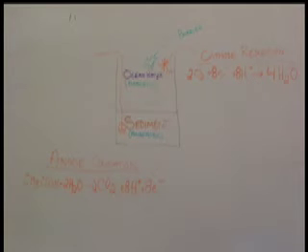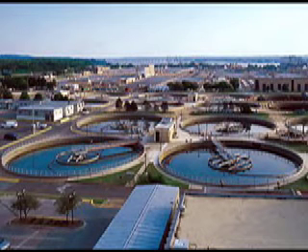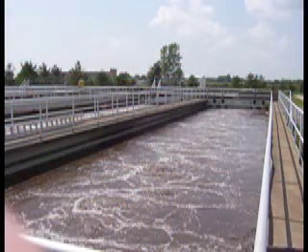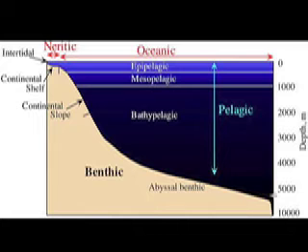Benthic microbial fuel cells are a relatively new development that has applications in wastewater treatment and energy production for treatment plants or in deep ocean locations. These cells utilize an anoxic and oxic region to create an electron potential difference so that electricity can be generated.